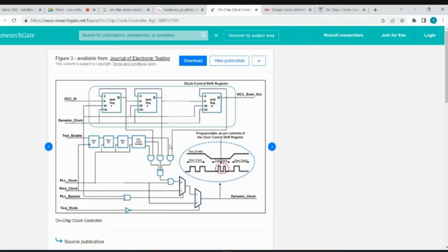For PLL, we might need a maximum of 5 or 6 clock pulses. You give that input during OCC insertion in the design, and the tool will generate that many flops accordingly. If you want to use a custom OCC, then you have to write the code to produce that many clock pulses.